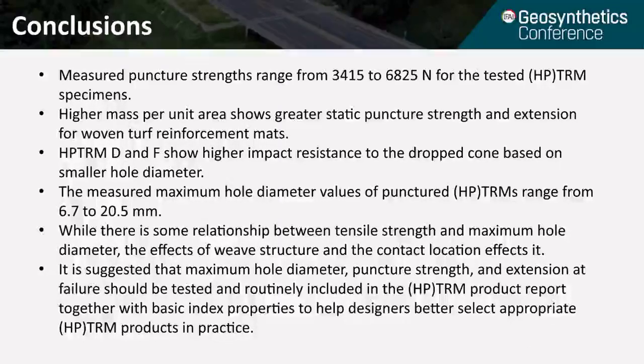From this study, we can observe the measured puncture strength ranges from 3,400 to 6,800 newtons for the tested TRM specimens. We can also observe the higher mass per unit area shows greater static puncture strength and extension for woven turf reinforcement mat.